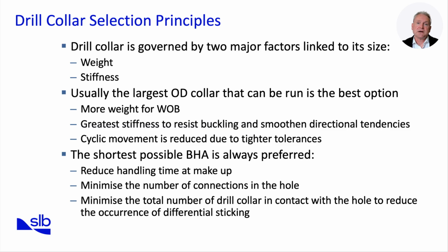Moreover, minimizing the total number of drill collars in contact with the wellbore decreases the risk of differential sticking, a major non-productive time issue in drilling operations. Ultimately, selecting the correct drill collar size is a balance between mechanical stability, operational efficiency, and risk mitigation.